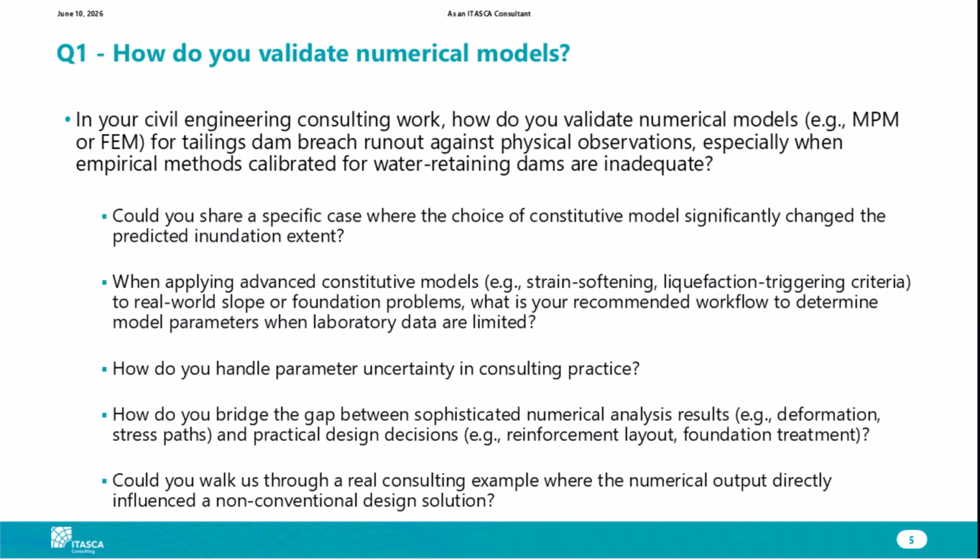So at the end of the day, what we are trying to do here, I don't really need to match a Brinch-Hansen bearing capacity. I don't need to match the p-y curve that is coming from Reese or anybody else. I need to understand how the system performs and behaves. That is our scope. So I don't need to reconcile anything. Once I'm confident in the approach and I manage the uncertainty to a tolerable value, then I'm okay with that.